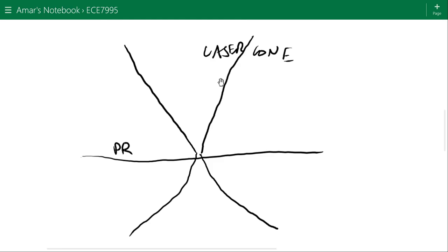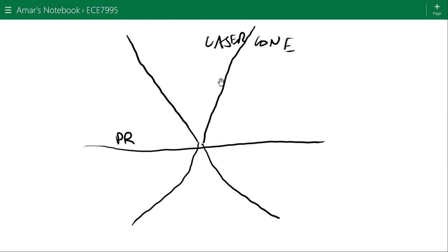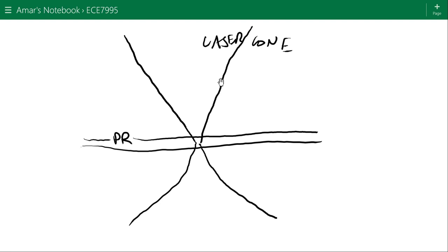Now, the conventional thinking would be that in conventional direct laser writing, wherever this beam hits the photoresist, those are the regions that are going to be exposed. Okay, but with the multiphoton approach, only the region right in the middle of the beam will be exposed, because that's where the highest intensity is. Only at the regions of highest intensity will you get enough photons being absorbed in the material or generated in the material to cause the cross-linking reaction to happen.